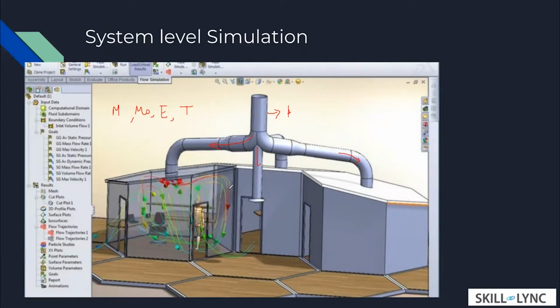So for example, if you feel like in a particular room, in certain areas it's hot and certain areas it's cold, that means the incoming air is not getting well mixed, right? So in that case, you can actually use CFD to maybe come up with clever solutions so that you diffuse air in all directions and you keep on oscillating this process to get a uniform mixture, right?